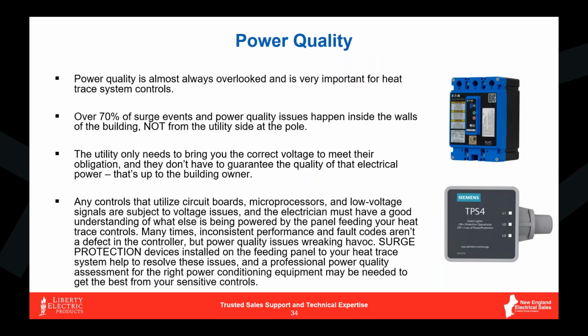And speaking of power quality, we've been recommending for years now that any entrance panels or distribution panels that you have feeding power to your heat tracing circuits, you should definitely be looking to put surge protection on it at minimum.